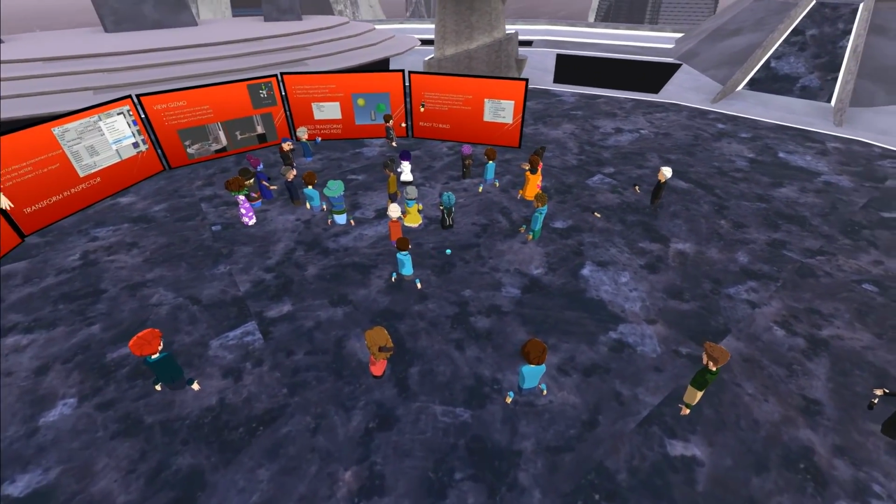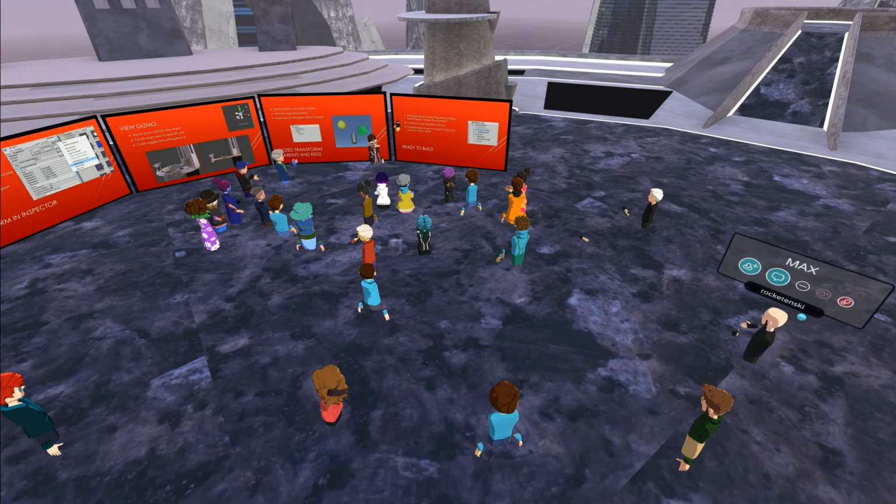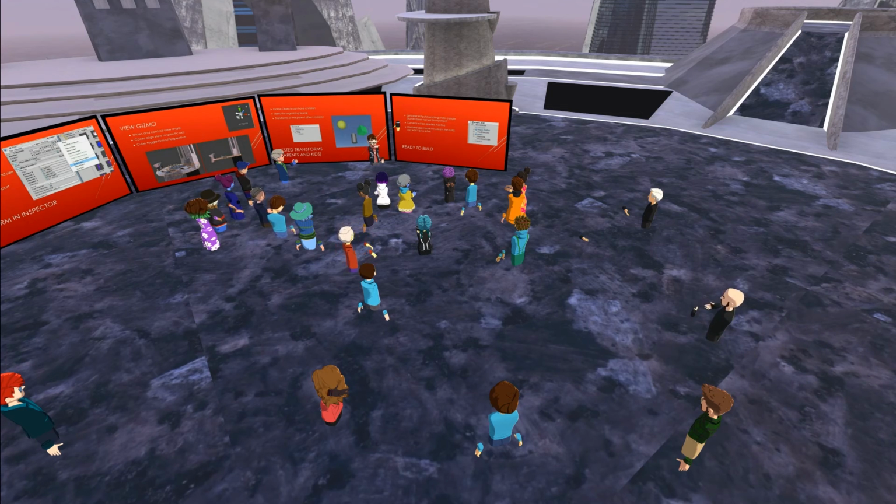Also, what Altspace is going to do is, unless I have unchecked the auto layer option in the uploader. So if I look under the build settings, there's an option for disable auto layer management. I don't remember exactly what it says. But if I don't check that, I let it do its auto layer thing, then it's going to move all of my objects onto the same layer. And that's fine. Let it do that, unless you have a particular reason to. That's not really going to be that big of a deal.